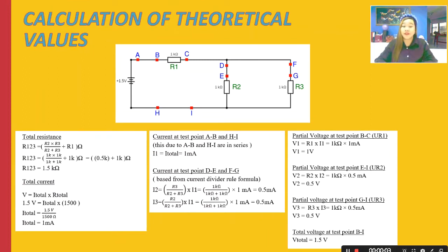Before we start our experiment, it is important to calculate the theoretical values first so we can select the correct range on our multimeter when doing our measurements.